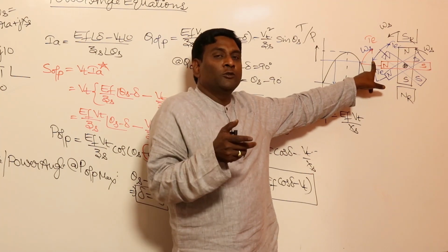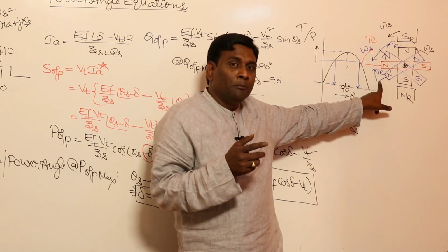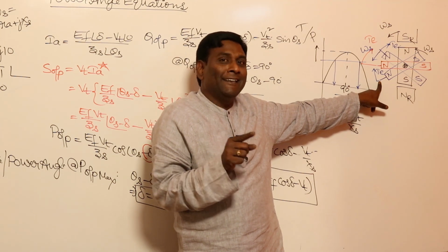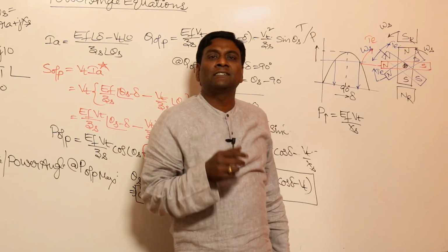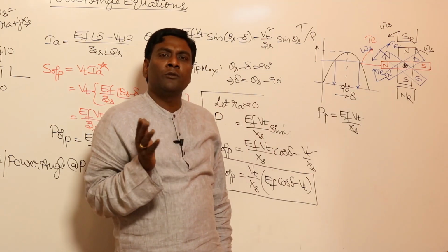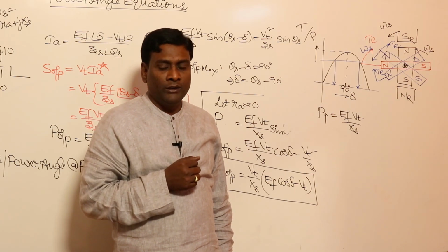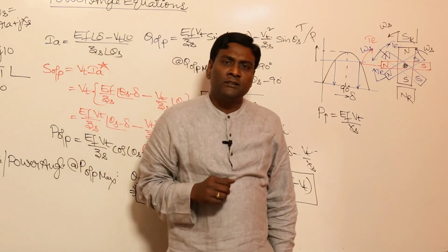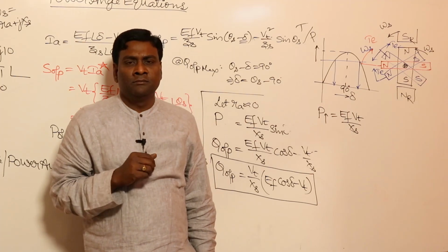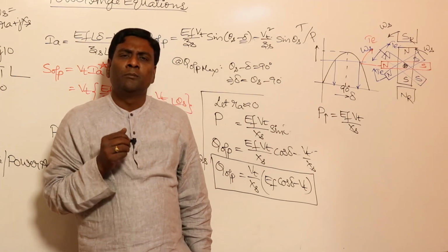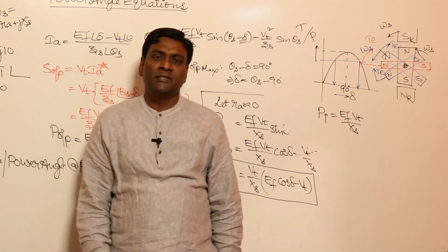So the back torque is reduced, but the prime mover torque is increased. That gives an accelerating torque, such that my rotor will continue to accelerate. With these characteristics we can directly connect to stability. We can directly connect to any part of the power system which is linked with the synchronous machine. We will see soon.